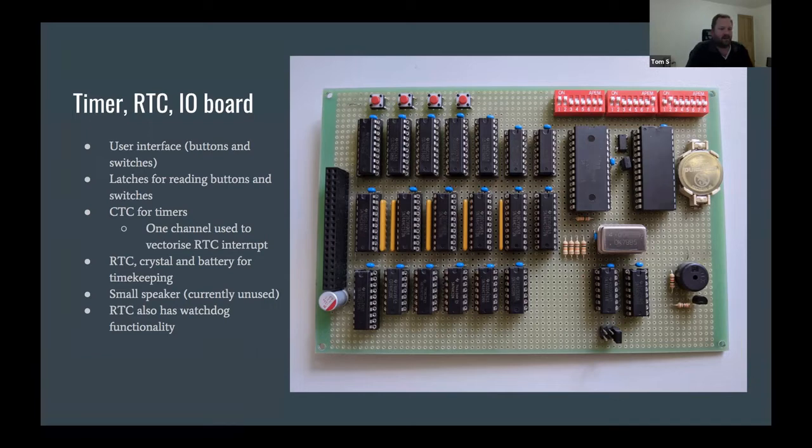The RTC, obviously not being a Z80 family peripheral, you basically have to just poll to find out if it was that device that caused an interrupt.